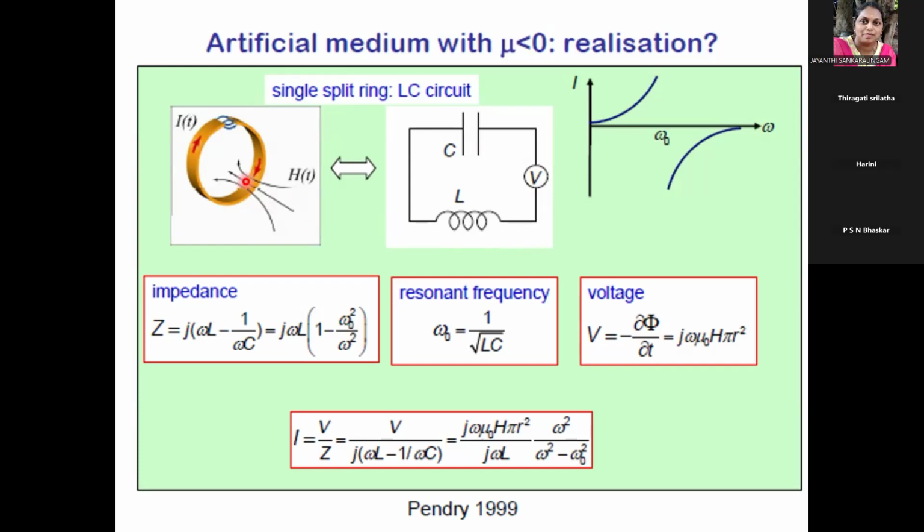Inductance effect means you have the magnetic field surrounding this conductor. Capacitance effect means you have the electric field between these spaces. So this E, the electric field present between these two spacings, is going to give the capacitance effect. The current flowing in this conductor will give the inductance, depending upon how much magnetic field is enclosed by this conductor.